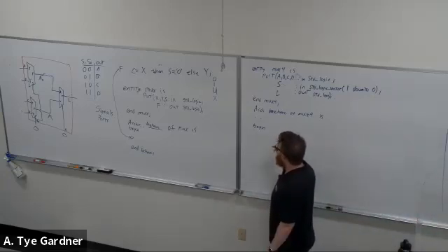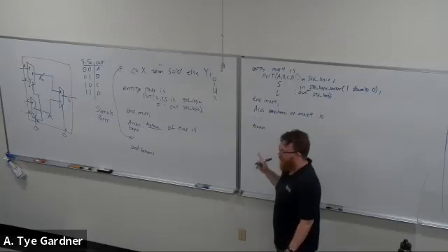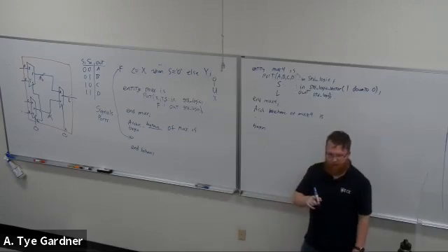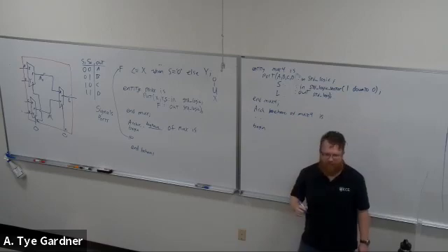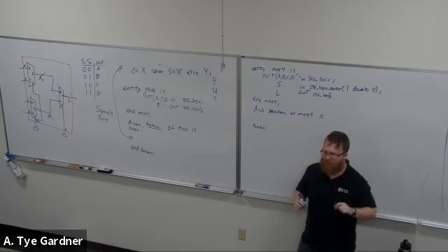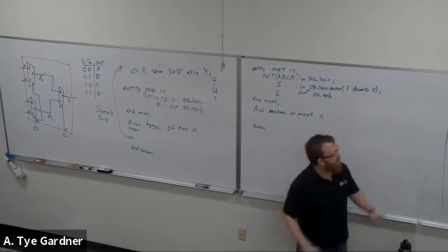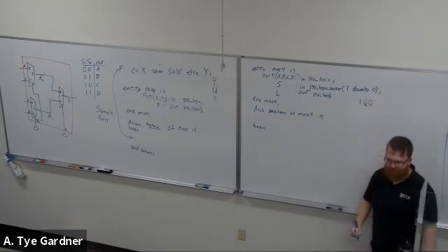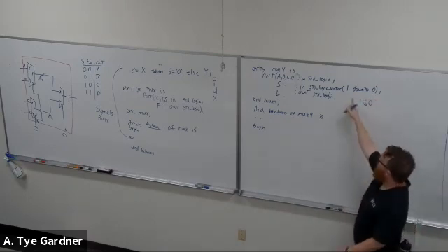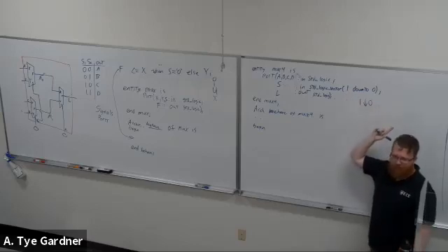Now, I have to do one more thing, which is, yes. Can you leave architecture abbreviated or do you have to take out the word? It will actually just make it for you. But yes, no, it's just a name. You could literally just put B there and it would be fine. Yes, the architecture has to be the full word. I will abbreviate things if I'm drawing, like down to, I will eventually switch to 1 down to 0. Okay, now, any idea why I'm doing 1 down to 0?